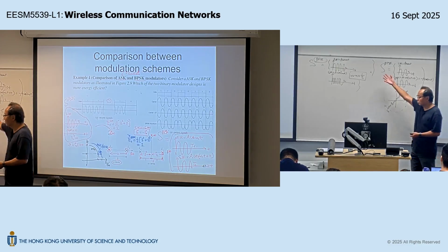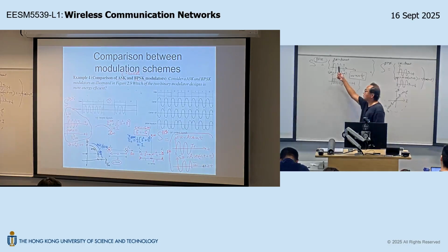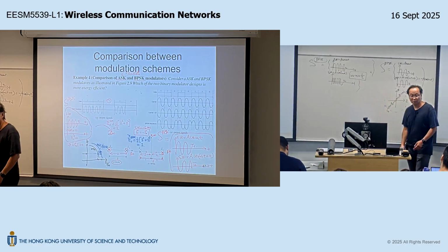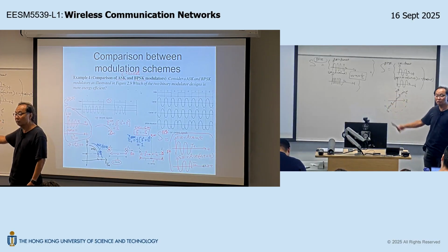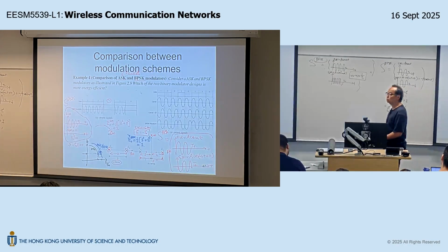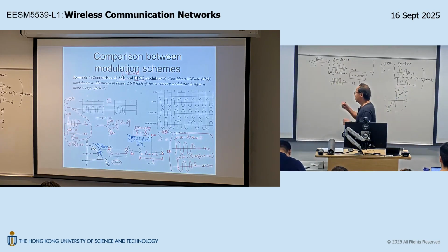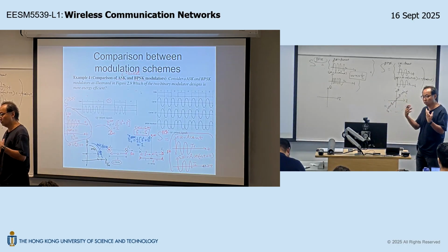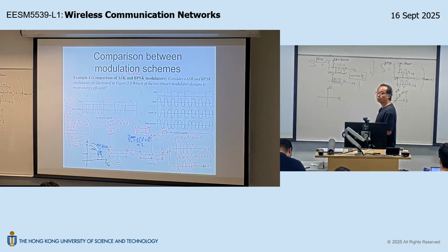Okay, but for the sake of this discussion, let's say I use the time domain specification for my other binary modulator, and this one deserves a name called BFSK. Again, which one is more energy efficient? If you look at the time domain waveform, it's very difficult for you to draw any useful intuition. Again, we use the same approach to consider this in the geometric domain. Let's say we have a 2-dimensional signal space. We don't worry about the detailed coordinates. We still focus on just extracting the first order constraints between the constellation points.